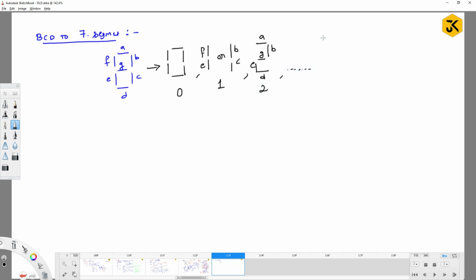If you would like to construct the number 9, what can you do? A, B, F, G, C. Right. If you want it to look like a G structure, you can take D also. If you don't want that structure, you can take only A, B, G, F, C. There is no problem, it looks like a 9. So with the help of this structure, I can get all the remaining numbers. This is what I call the 7-segment code.